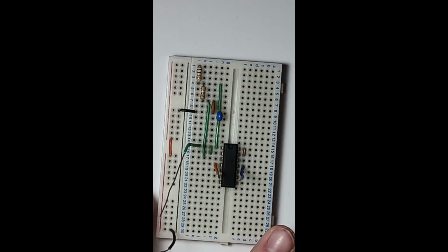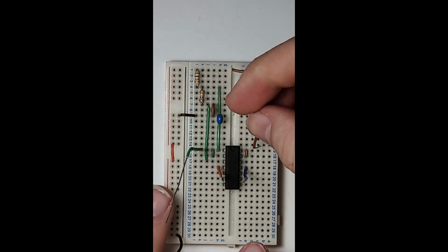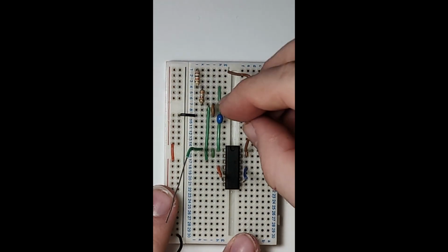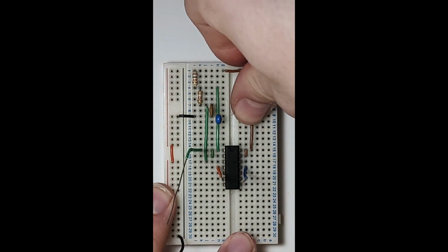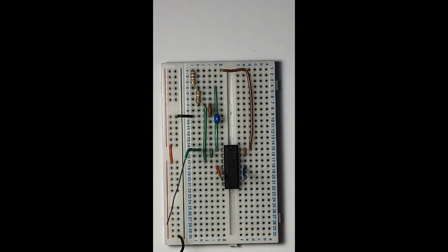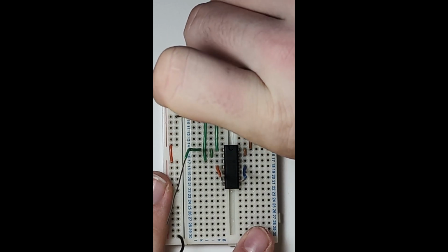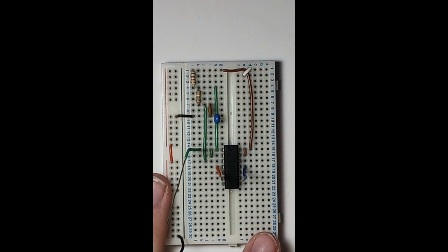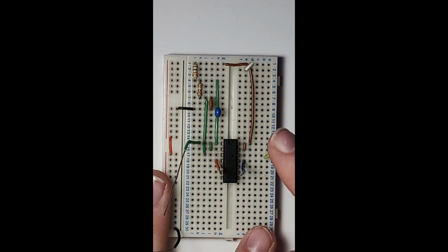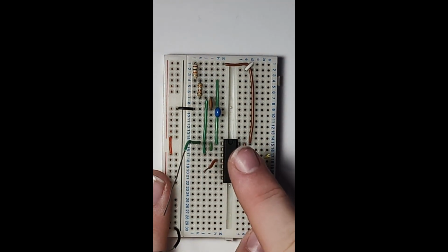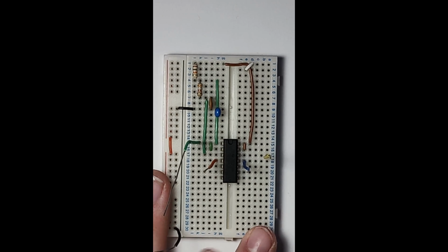No, just like that. And then we just connect the output of that to the input of the Sallen-Key, along with this white wire just to hold down that longer ground cable. And then we have an input wire here, so that you can input your signal here. You power the op amp with positive and negative 15 volts. You've got it grounded here, and then the output will be here.